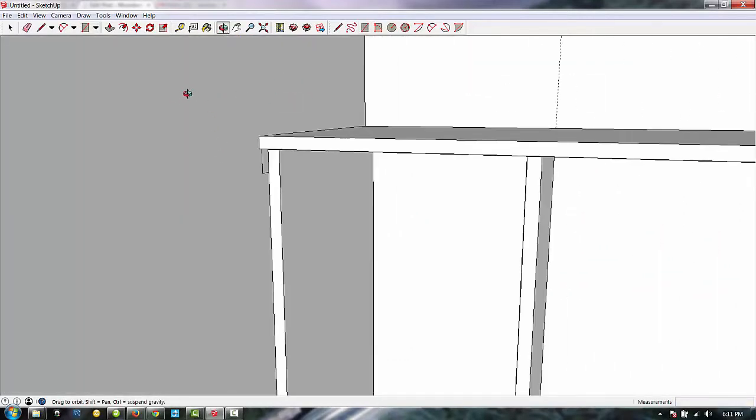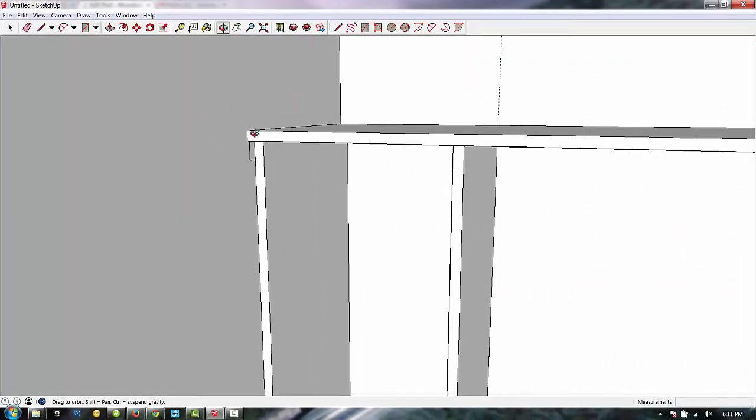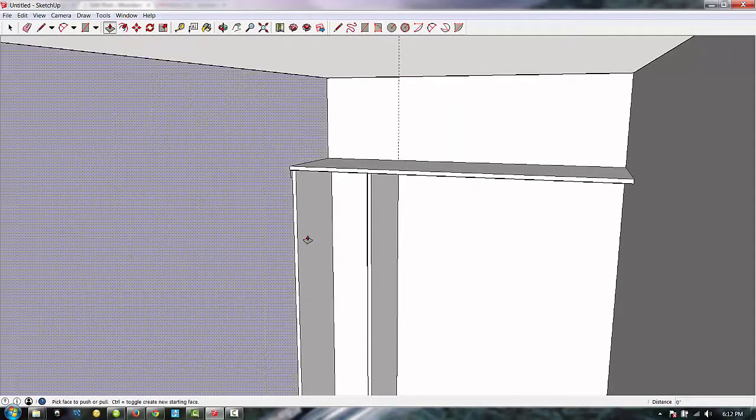One thing when you're spanning a wide area, even 4 feet, it's not a bad idea to put a cleat at the back side of the wall, like a 1x2 cleat, and in this case a 1x2 piece that I'll join up with some glue and screws, just to give rigidity or stability to that object. It's also a much better look in my opinion.